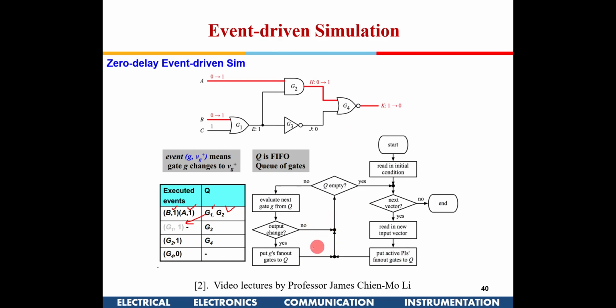So it is much faster. Now, we are talking about only 3 gates, but in a very big circuit, maybe 80% of the circuit may not be getting activated at all because of certain input test vectors. If you run a compiled-code simulator, it will run the entire program and recalculate the output at each node, whereas this will be much faster.